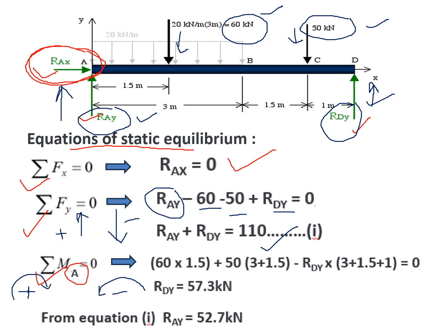Now we see this is the point. I make that point a little dark. This is the point which we take, so you have to focus on this point. First we identify the forces whose line of action passes through A, because the forces whose line of action passes through A will not contribute any moment. The rotational tendency of that force will be 0 because the distance is 0.